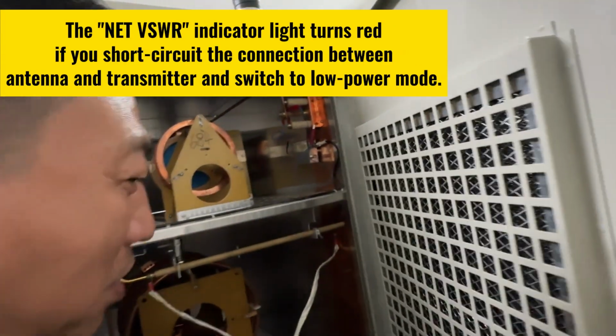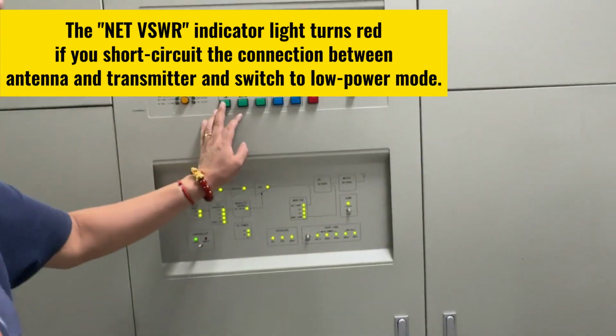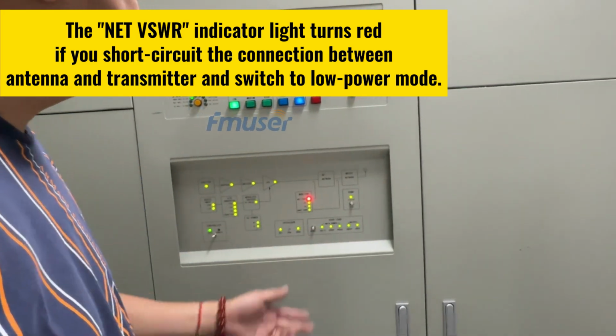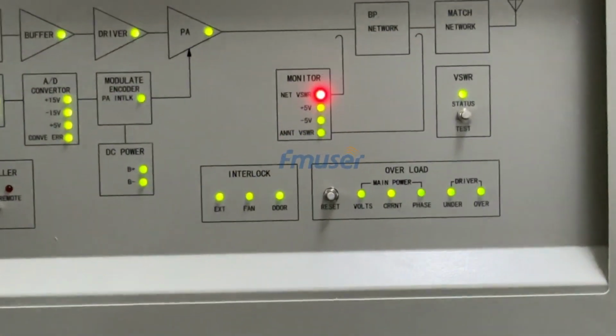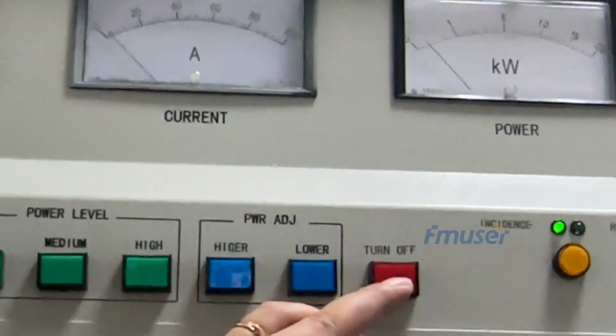In a scenario where the transmitter is operating normally, if we intentionally short-circuit the connection between the antenna and the transmitter and switch to a low power mode for testing, the net VSWR indicator light on the monitoring module will also turn red. This serves as a prompt that the antenna's VSWR is excessively high. Step number 6.